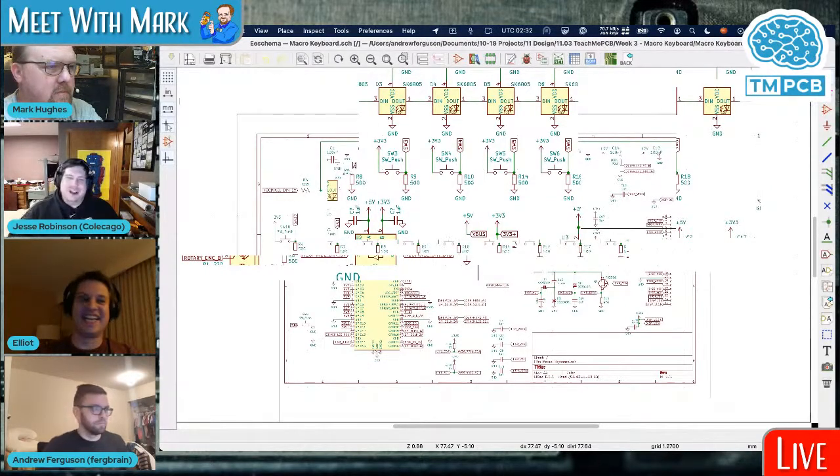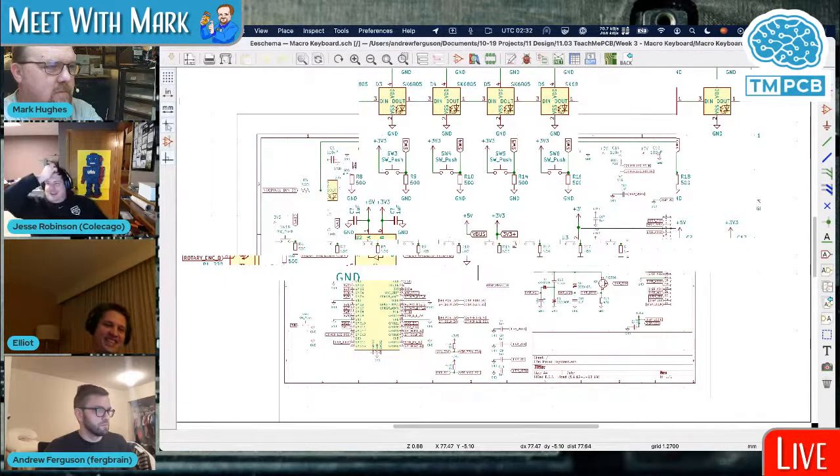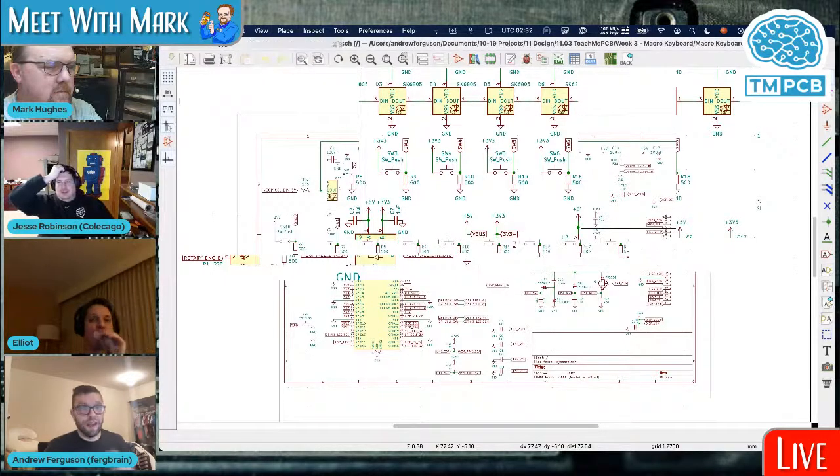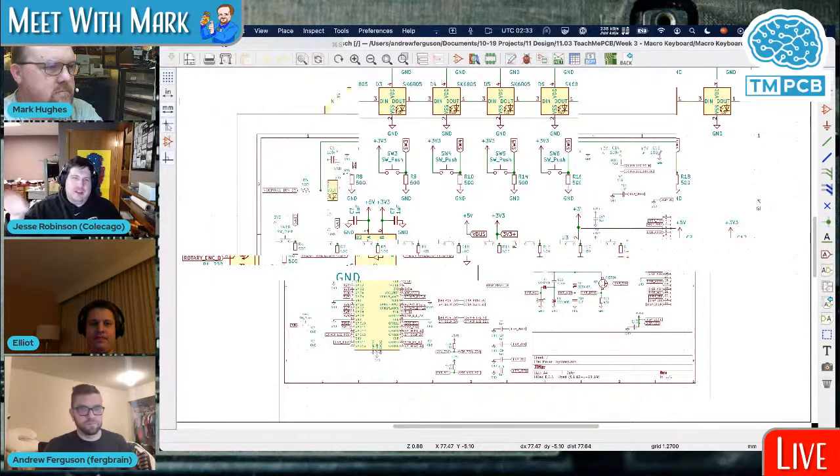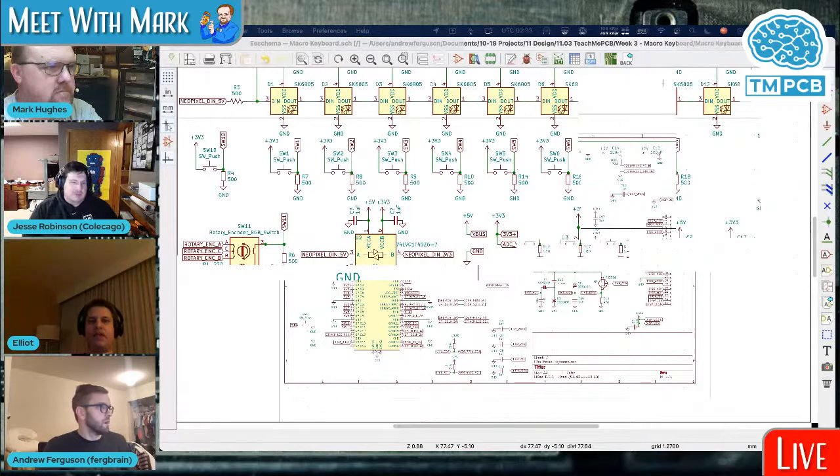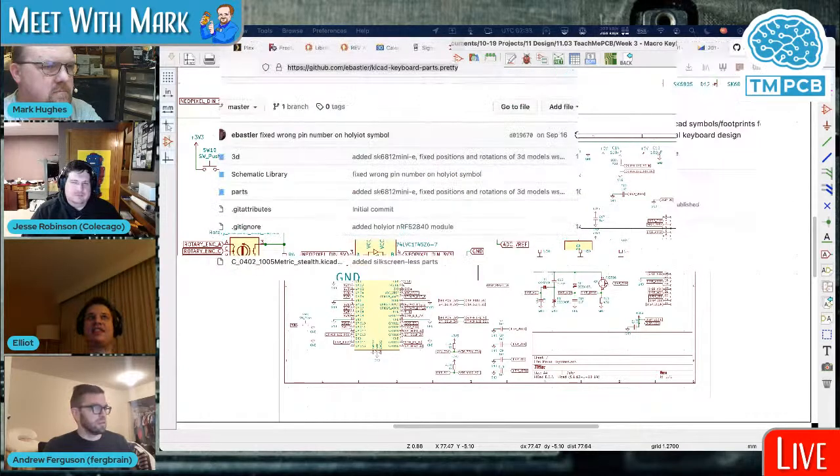So pin types on your well, I hate pin types. I don't use pin types. But when you do your power, like your power and ground, you need to add power flags. I think it has something to do with simulation things. Otherwise, by default, you shouldn't have to do that to not give you DRCs. That's dumb. Yeah, if you use the default, the included power symbols from the libraries, there is a setting.